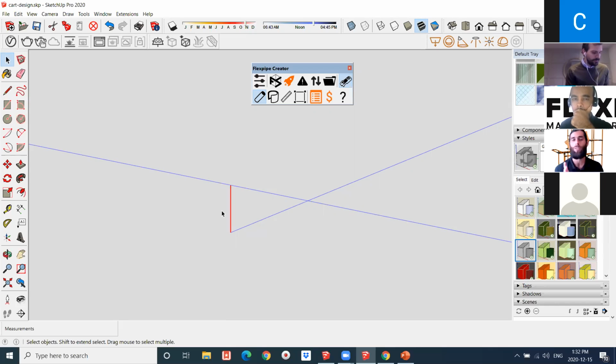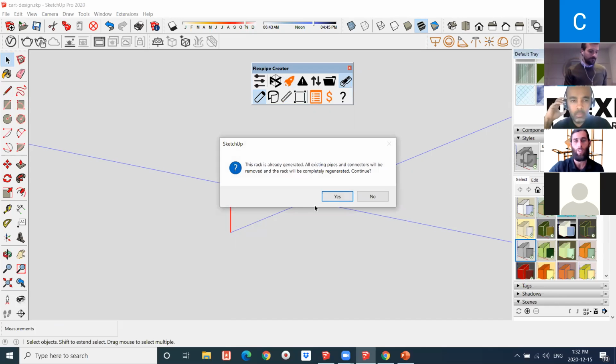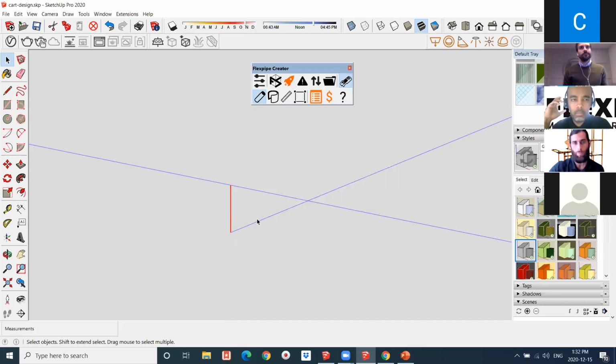So it's just a matter of understanding what the distance center to center is going to be for those two pipes to be joined together. So in this case, 1 inch and 9/16 is going to give us center to center, where we're going to be able to, again, generate and create the spacer joint.